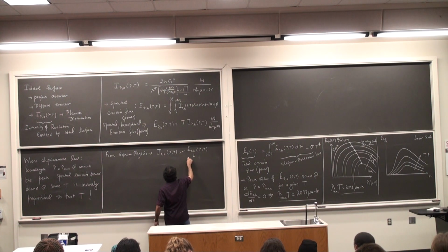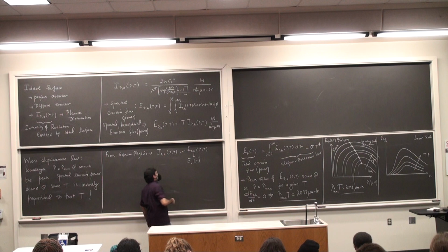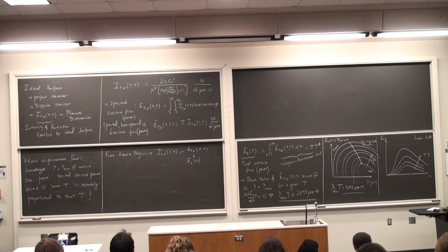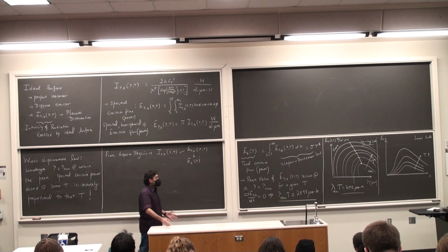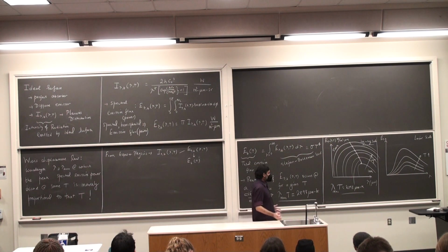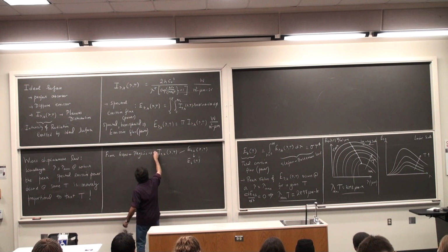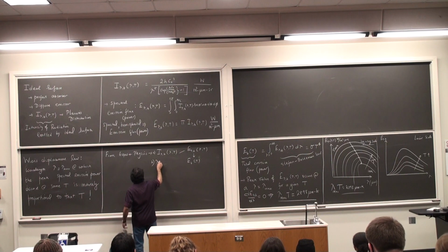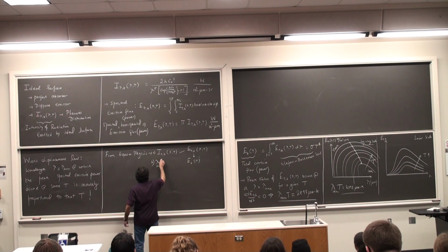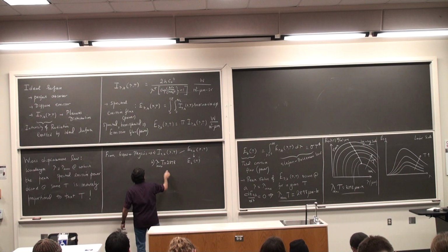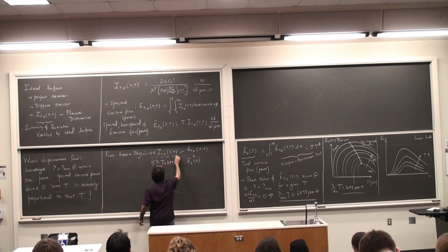This is completely well understood, and we also know, from Wien's law of displacement, given a particular temperature, what is the wavelength at which the spectral emissive flux is a maximum. So that's the second set of relationships that we will need, lambda max times T, 2898.